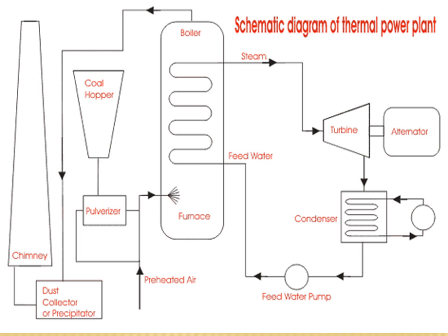Now first we will see the coal and ash circuit, which is located in this diagram on the left hand side. In this circuit, the coal from the storage is fed to the boiler through coal handling equipment for the generation of steam. Ash produced due to the combustion of coal is removed and transferred to the ash storage through the ash handling system.